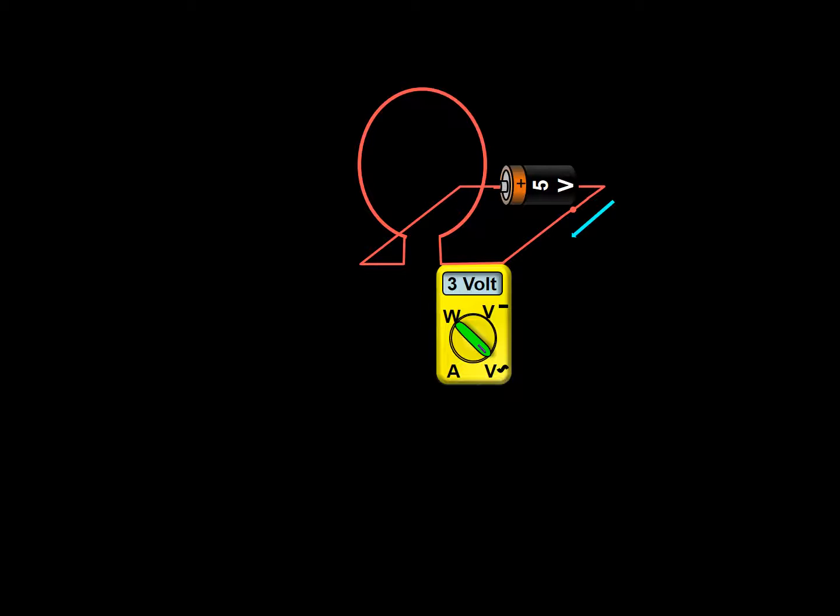The closing of the primary circuit allows electrons to flow through the circuit. The aqua arrow represents the electron flow and the direction of the flow. Notice at this point the voltmeter is showing an increase in voltage, but only of 3 volts. The reason voltage has not gone up to 5 volts immediately is because as electrons flow through the inductive element of the circuit, some of the charges in the electrons are converted into magnetic force.